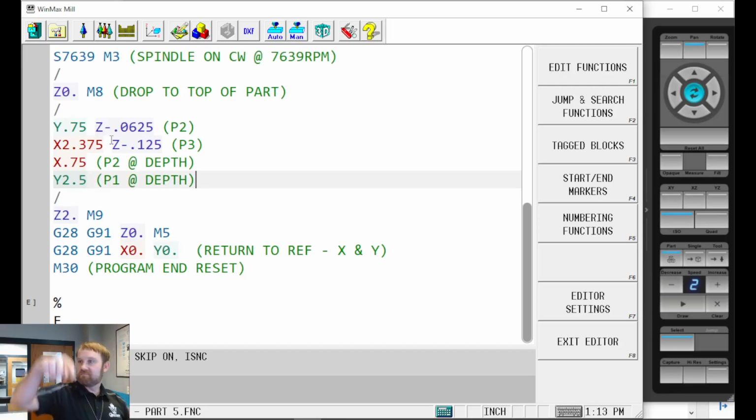So we're milling a slot. Now I will tell you this, and you've probably been taught this back there, and you're going to get taught it out here. It is very rare that you're going to mill something the size of the tool that you're cutting it with, meaning it's not a great machining practice to make a 1/2 inch slot with a 1/2 inch tool. Now, if it's just like a clearance slot or something, yeah, just slot it out. But typically, we're not working on Grandpa's farm.